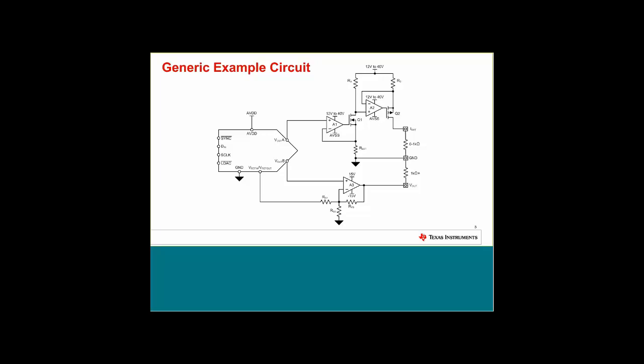Meanwhile, for the bottom half of the circuit, we have just a simple gain stage, because typically the DACs that are available are SPI interfaced and relatively low voltage devices operating off of maybe 5.5 or so volts with output spans from 0 to 2.5 or 0 to 5 volts. For industrial, we want to see at most plus or minus 12 volts. So we need a simple gain stage in order to realize those output spans. The minimum impedance for the voltage output is about 1 kiloohm and upward. You typically don't see anything less than 1 kiloohm for the voltage output.